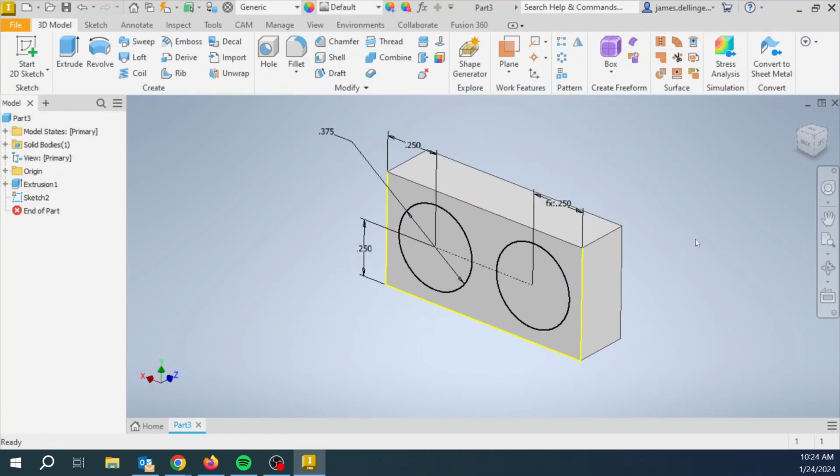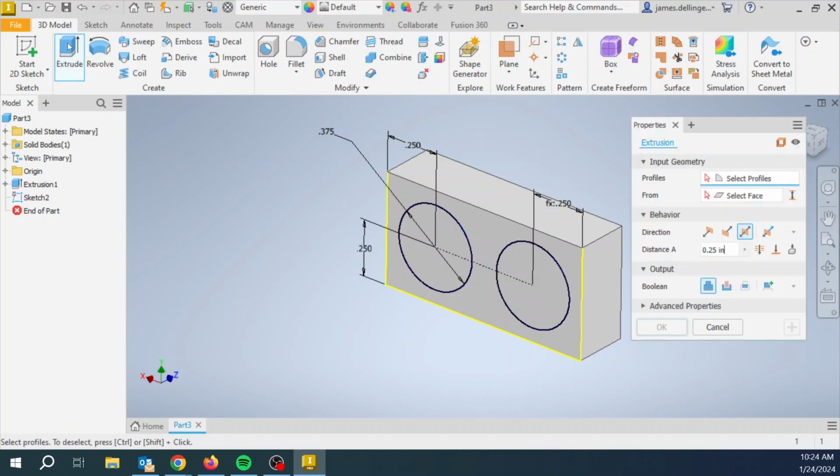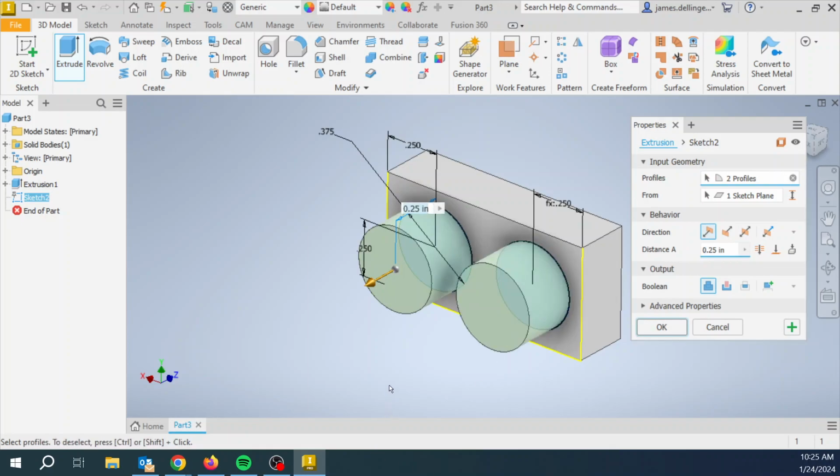So let's hit finish, and then we're going to go to extrude. Now on this extrude, nothing automatically extrudes, and the reason is it's waiting for us to say, what do we want to extrude? So I've got this closed area and I've got this closed area. They kind of highlight and shade. I really want both of them, and so I can click those two and kind of turn it into my Lego brick, okay?